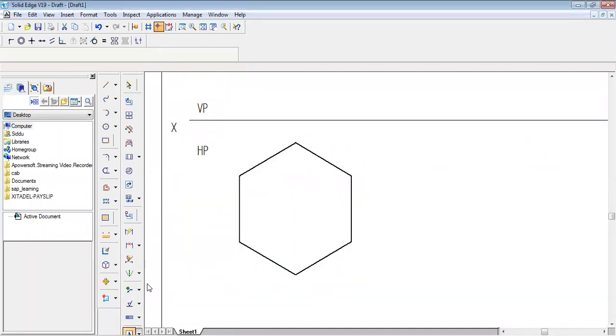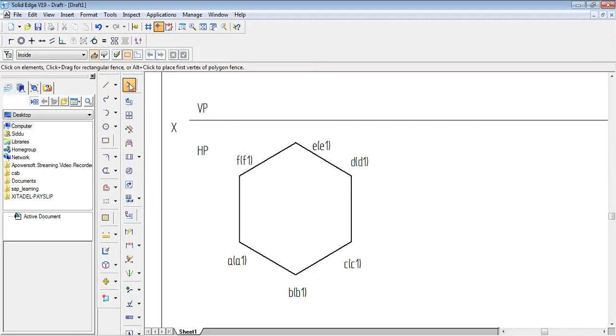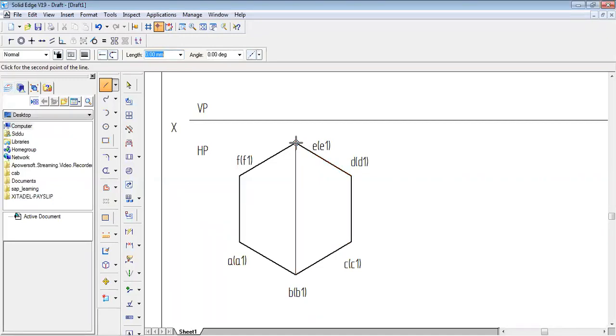We know that to name a prism, we use A and A1, B and B1. I will not explain again and again how we are supposed to name it for prisms and why we do all that; I've already explained. So D and D1, but the naming is very, very important in this case because to locate all the points it is going to be very useful. Without naming it, it gets messed up. All being done, now we have to identify the center line within this by connecting the opposite endpoints.